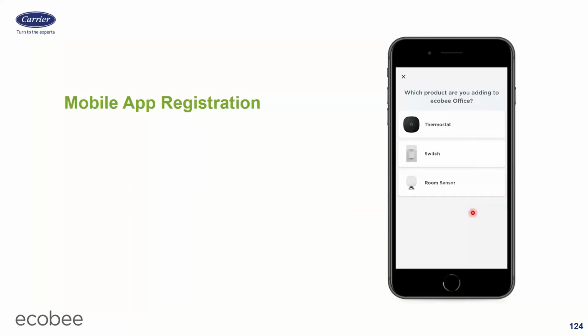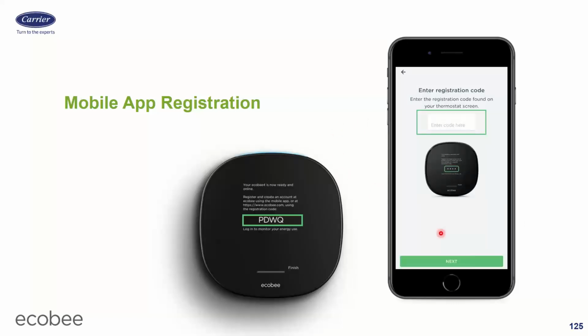It's going to ask you what you're actually adding. In our case, we'll be adding a thermostat because we're HVAC people. It'll ask you thermostat, switch, remote room sensor, which I might be doing if I'm adding a remote room sensor onto that thermostat. And now it also asks you if you're adding a camera because they came out with cameras this summer. On the thermostat side, after I connect to the Wi-Fi, the next thing the thermostat will tell me is this 4-digit code. I take the 4-digit code from the thermostat and I punch it here on the app, and that's what pairs the two things together, right?